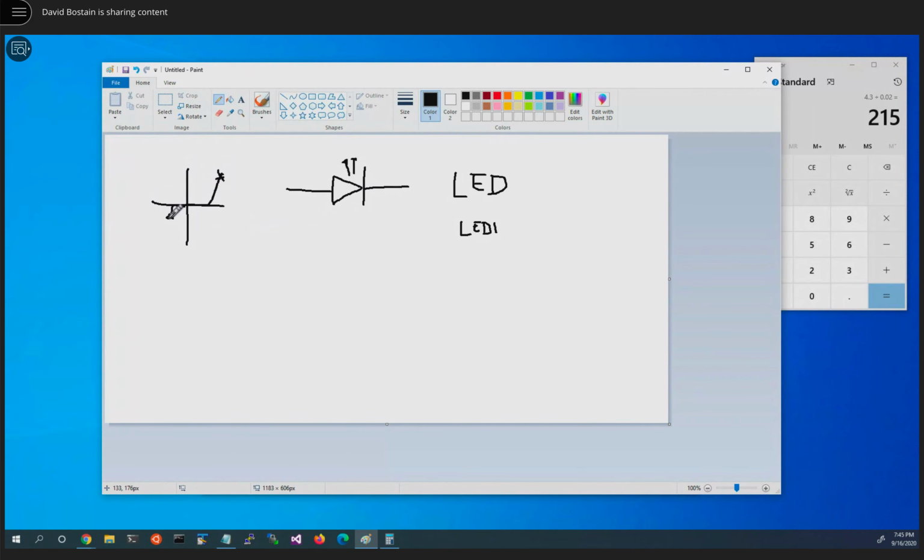So it has to be handled with a little more care. But again, this is the anode, that's the cathode. Current would flow this way. And if current is flowing above a certain amount, light is seen. If it's too much, it burns up, never shows light again. Or if it's put in backwards and the voltage is high, it will often get burned up as well.